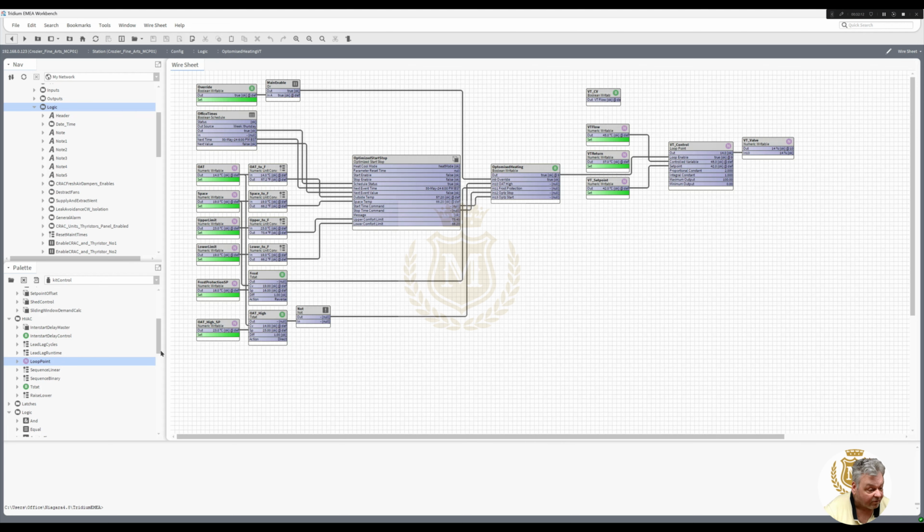And then we can use a numeric switch, a Boolean switch, sorry, a numeric switch, so that's VT flow in there, which is false. So we take our VT flow and we put it into false. We take our VT return and we put it into true.